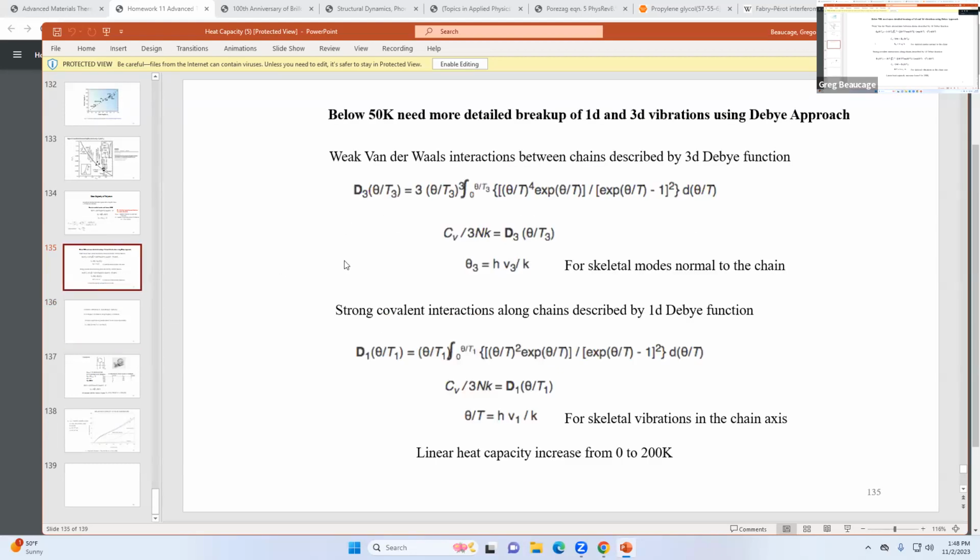Does it depend on the crystallinity of the polymer? These are liquid, like in liquids, like amorphous polymer. They're using polystyrene, it doesn't crystallize. If you make it tactic, it can crystallize. Basically the kind that you have for a Scotch tape container, that's amorphous. Any polymer that is clear is amorphous. And the crystalline ones are like white, like a milk jug. Semi-crystalline anyway, but so yeah, it wouldn't matter if it's crystalline.